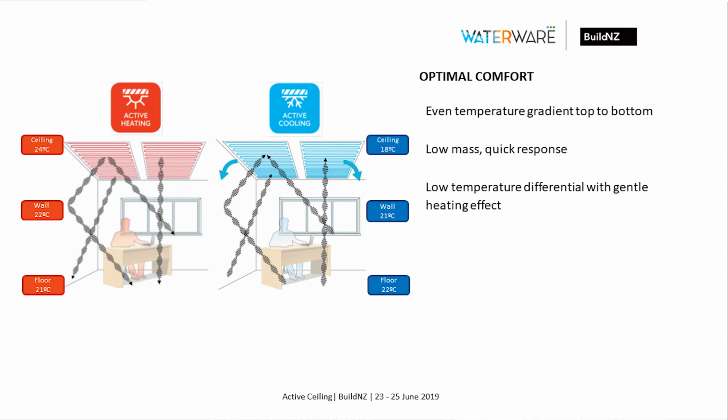It's not like an air-based system or, to a degree, a radiator-based system where you've got a smaller surface area, and so you have to operate with a bigger difference in temperature to affect the whole room. With an air-based system, if you're sitting right underneath a duct and the duct's blowing on you, you'll be too cold if we're in cooling mode. You have a Goldilocks zone of about 1 meter where you're comfortable.